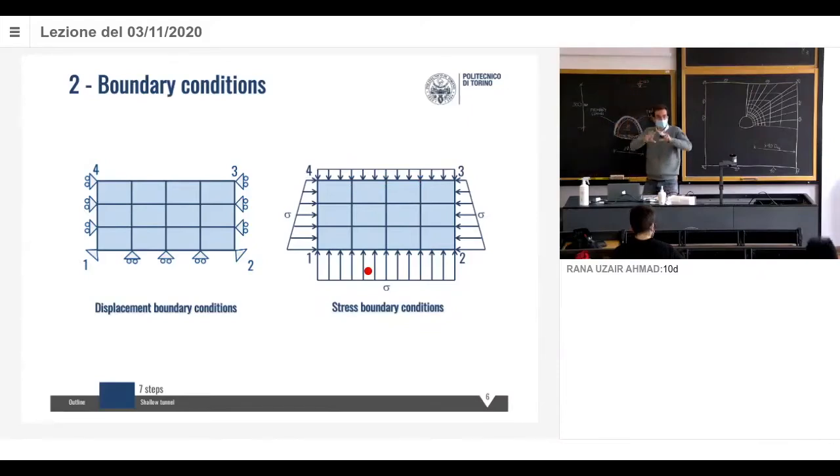We are engineers. We like to see the distributed load is applied there, distributed good. But then in the computation process, that distributed load will become point forces applied to the nodes. So we will need to compute this. The software is going to do it 99% of the time. But in general, we need to compute those forces and apply them to the nodes.